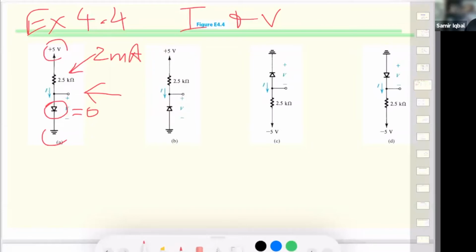All right, the second one is now reverse biased, right? So this is an open circuit, which means whatever voltage gets to this node is going to show across these guys, and that is 5 volt. Because now these two resistances are in parallel, and if they are parallel, the voltage across them would be the same. Now, what is the current here? Current in an open circuit would be 0 amp, because there is no place for this current to go. Are you with me so far?